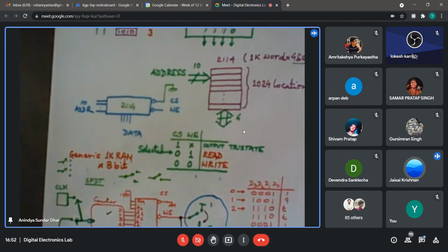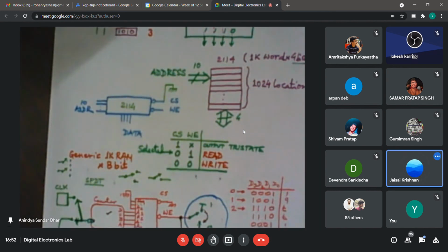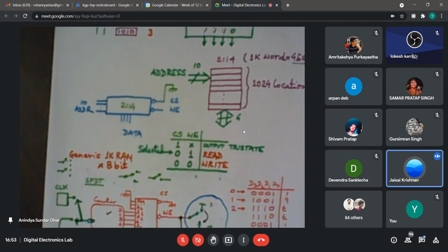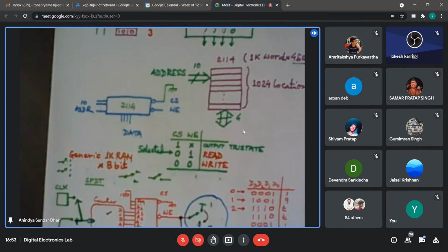Sir, can you tell us the list of ICs, like what about the RAM? Actually, in the lab we would use 2114, but here there is no such IC. Do you have your simulator in front of you right now? I'm on a different laptop actually. Okay, so you need to go into the devices, then browse, and you are probably choosing either digital by number or digital by function. I do not know which one you generally use.